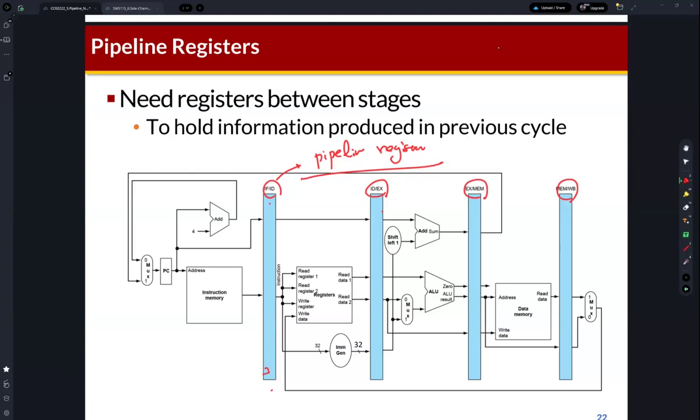So, this is the D flip-flop. Actually, the clock signals are connected to these pipeline registers, okay? And then we can call this pipeline register the instruction fetch / ID. So it represents the pipeline register located between the instruction fetch and instruction decoding stages. Okay, and then we can use the same convention like the ID / EX.